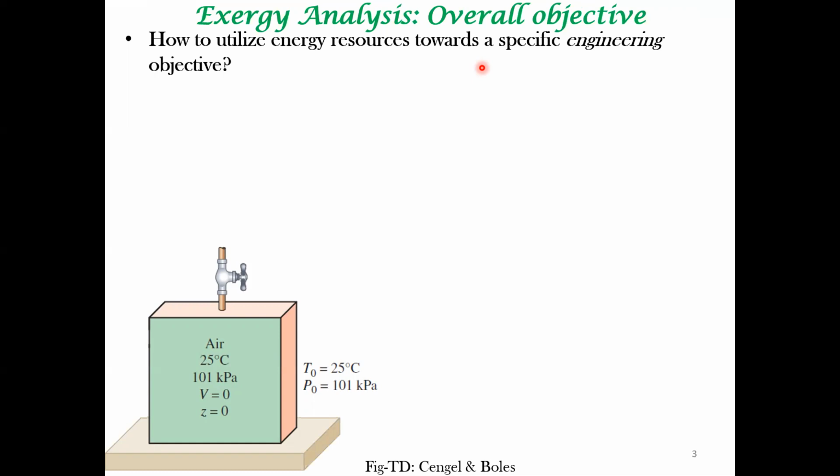Whenever we want to do some work, for example, here you have air. Using this air, we can obtain work. However, if certain properties of the air are the same as the ambient atmosphere, then the work potential of the system is zero. For example, in this case, the temperature of the air is the same as the temperature of the ambience. The pressure is also the same. So there cannot be heat transfer, and there cannot be a difference in mechanical forces on either side, which would facilitate pumping of liquids.